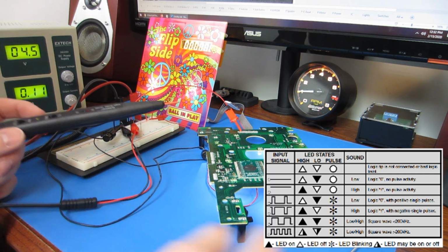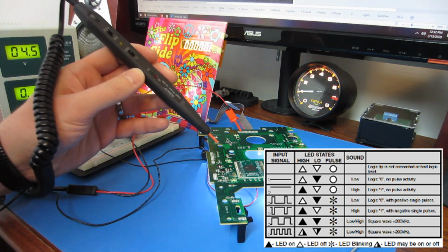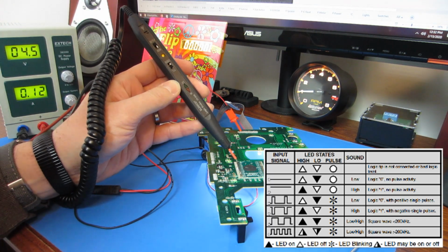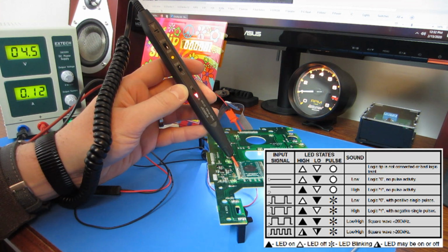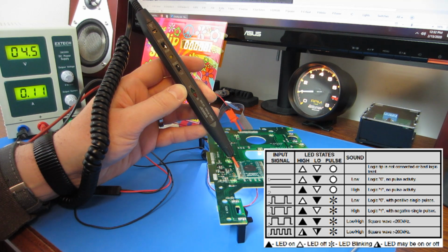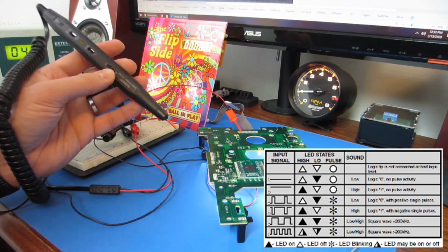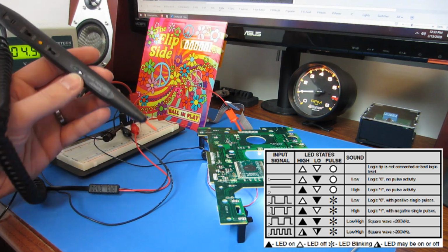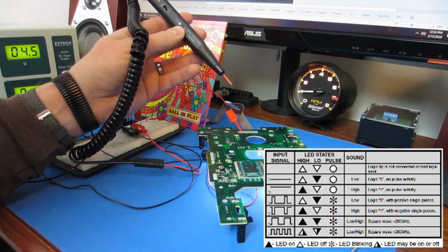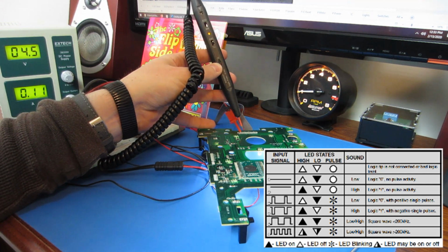And we'll just take a look at signals that I know are high and I know are low. So we'll look at VCC and ground on the micro. So of course VCC is high, and ground is going to be low. Now let's take a look at these SPI signals. I'm going to do chip select first.